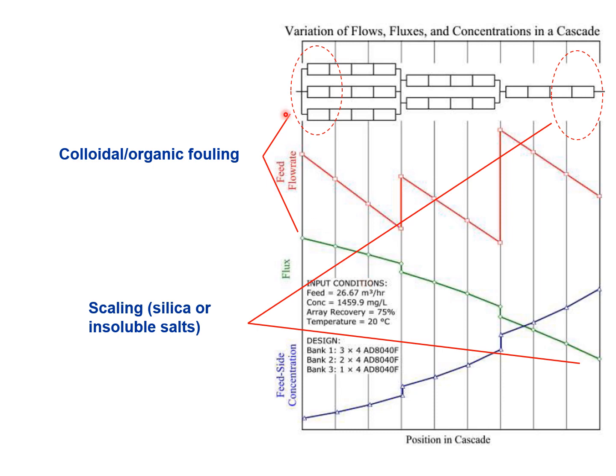So we need to look at the water chemistry. We already studied the essential water parameters to predict what the inorganic scaling could be when you recover very high water flux at the last stage. So how can we prevent this scaling and fouling, so we can design a better RO module and element.